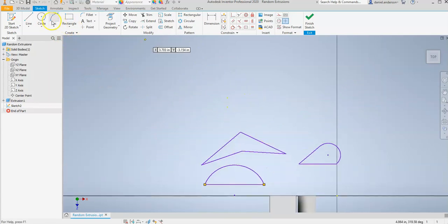And let's just draw something with just our arc tool. So what I'm going to do is click and drag and click again, and then drag and create that first arc. And then I'm going to click there and drag and click again and draw this second arc. And then I can find that end, make sure I get that green dot. I want to click, drag to some random place and drag again, and then click. And then let's do it one more time.